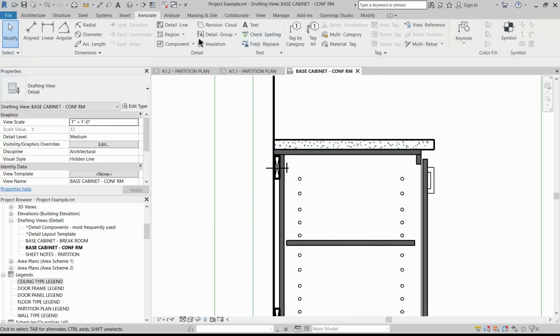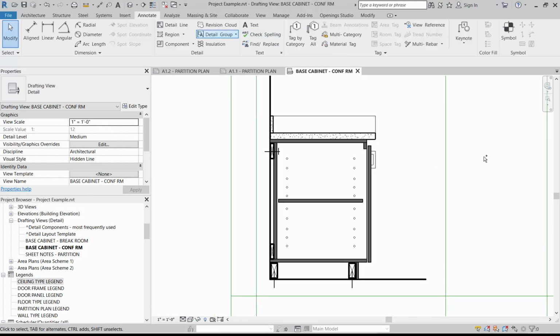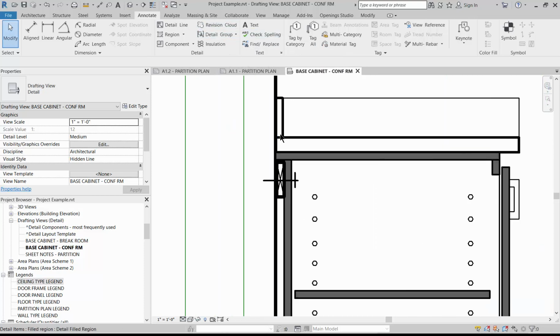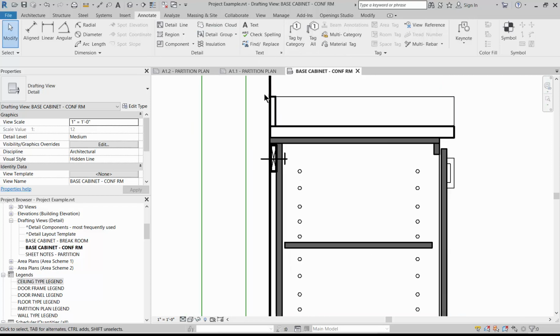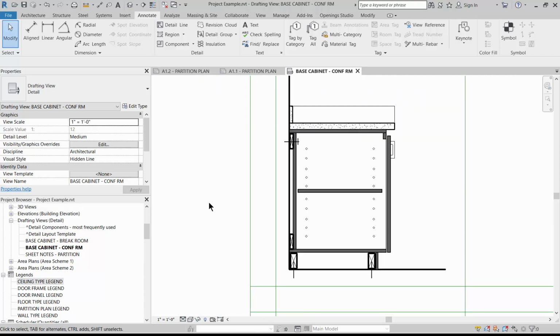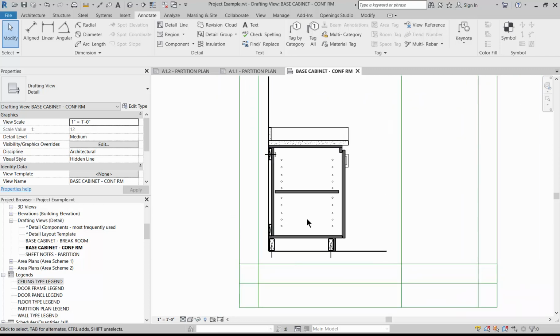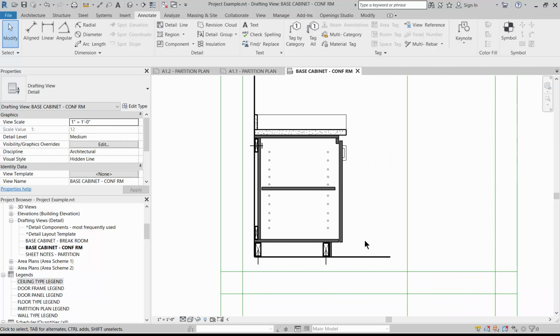And don't forget the backsplash and also a side splash in elevation if you have one. So the backsplash is usually a separate piece, so we would have 2 separate sections for that. And then finally side splash would be our thinnest line viewed in elevation. And then this is the drafting portion of the standard base cabinet. Now the next steps, we would go and annotate it and possibly cross-reference additional details in the next step.